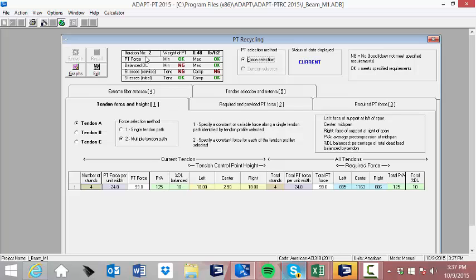So it shows an upper left block where it's just checking the different serviceability requirements, and it's either no good or okay. For PT force, this is just the pre-compression range that we entered, which was 125 to 300. The balance loading range between 50% and 100. So here you can see the design does not satisfy the balance loading range. The balance loading is actually 10%, not 50.